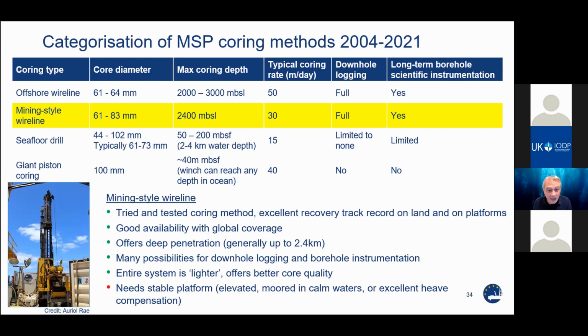So you can actually use these systems if you have excellent heave compensation, but your penetration will be limited in such a setup, probably to maybe just a few hundred meters due to the weaker pipe that's being used. And that weaker pipe has to handle more movement under a heave compensated scenario.